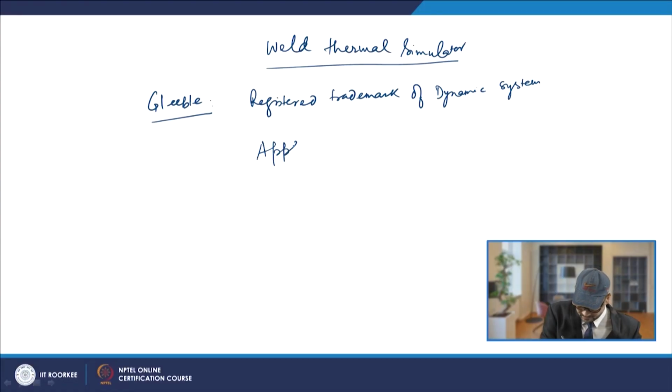The jaw is water cooled and holds the specimen. You also have a thermocouple spot welded to the middle of the specimen, and accordingly you can experience the thermal history, the simulation of how the specific thermal cycle is duplicated. So there are many applications of the weld thermal simulator.